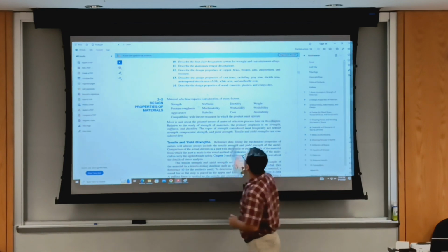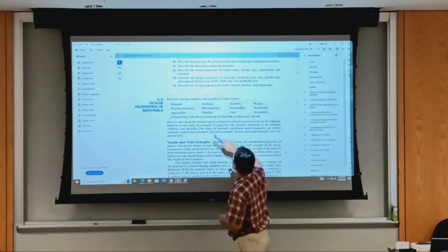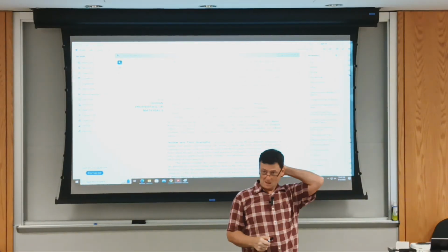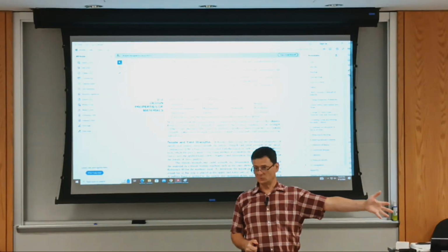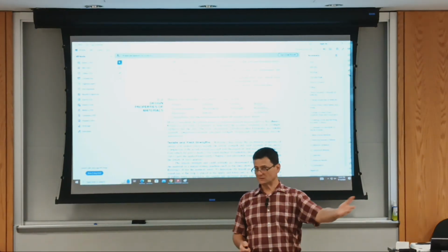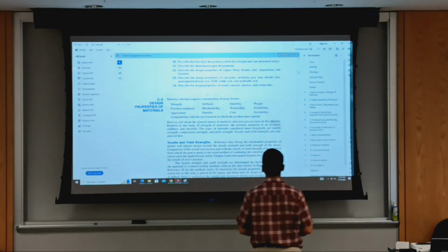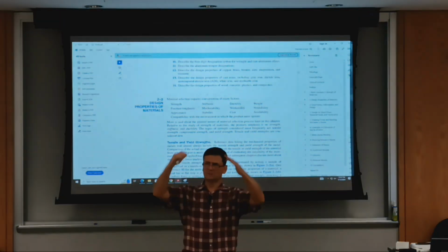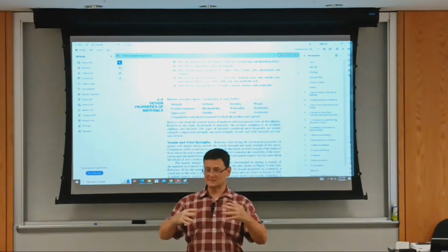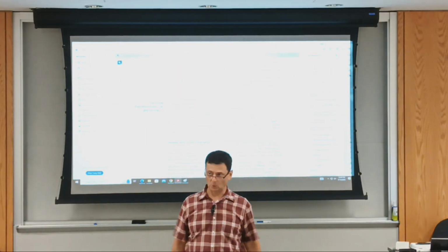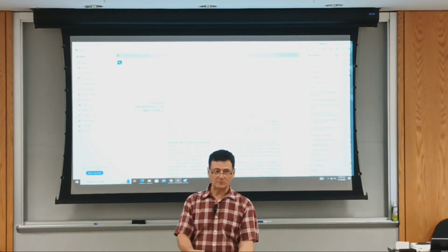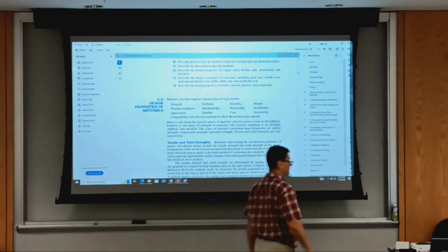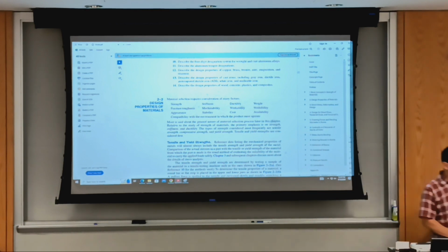Okay, and then compatibility with the environment and with the other materials in the component. So you design for what? For maritime use, pieces to be used on a boat or on a yacht is one. For example, I know of a case with a ceiling that collapsed. They used stainless. It was a cover for a swimming pool, but they add chlorine to the swimming pool, and that chlorine corrodes the stainless, and the roof collapsed after some time.